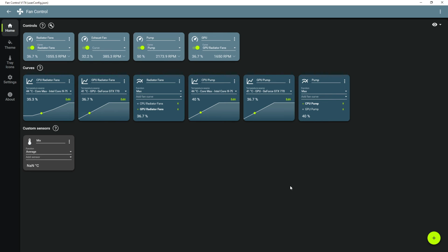Now mix pretty much has one major use case in water cooling, especially, and some of you may want to do a fan control strategy where you control the radiator fans based on the delta T of the coolant versus the ambient air. You would need a motherboard that has external temp sensors for this, by the way.